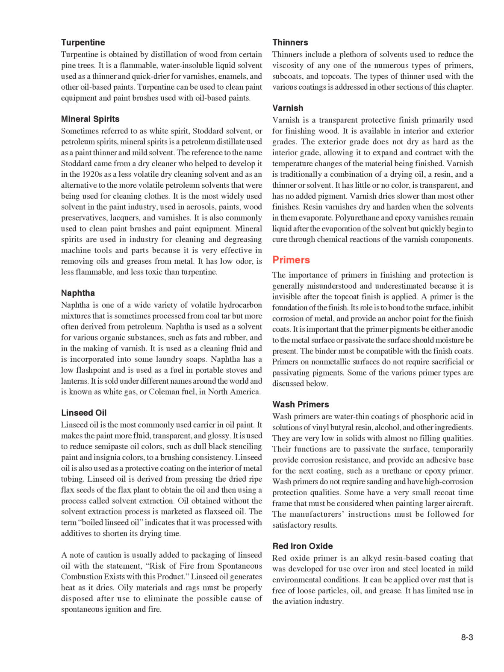Some have a very small recoat time frame that must be considered when painting larger aircraft. The manufacturer's instructions must be followed for satisfactory results. Red iron oxide. Red oxide primer is an alkyd resin-based coating that was developed for use over iron and steel located in mild environmental conditions. It can be applied over rust that is free of loose particles, oil, and grease. It has limited use in the aviation industry.